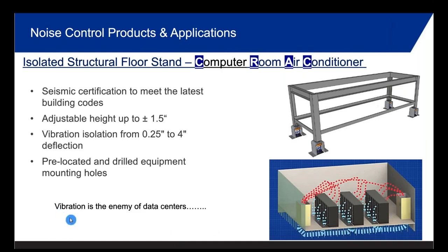And I put a little note down here, you'll see on this in the next slide, because I saw it in a number of things. I even saw it in some interviews of some data center facility managers: vibration is the enemy of data centers. And it's very important. So whether it's the UPS systems, whether it's the servers and all that, and then of course seismic is an issue. So we have here, these can adjust with flexibility of height, vibration from a 1/4 inch to 4-inch deflection for added efficiency, and different cutoff frequencies, and everything's mounted, drilled, ready to go for you. So those are great. They're very applicable. We see them in a lot of data centers.